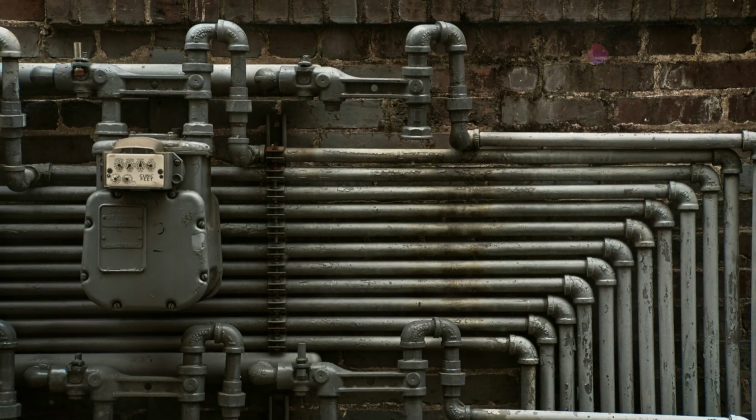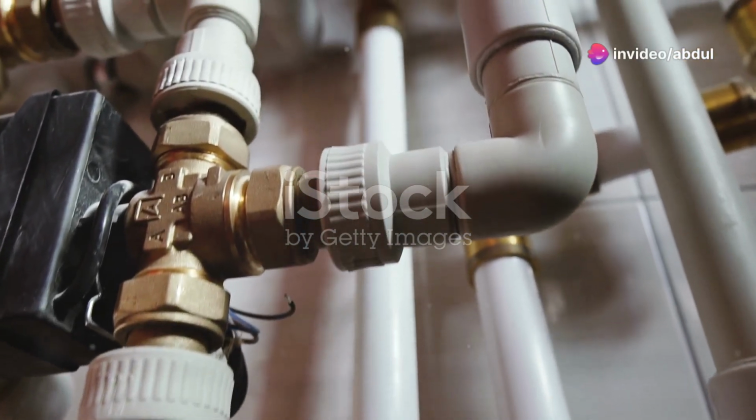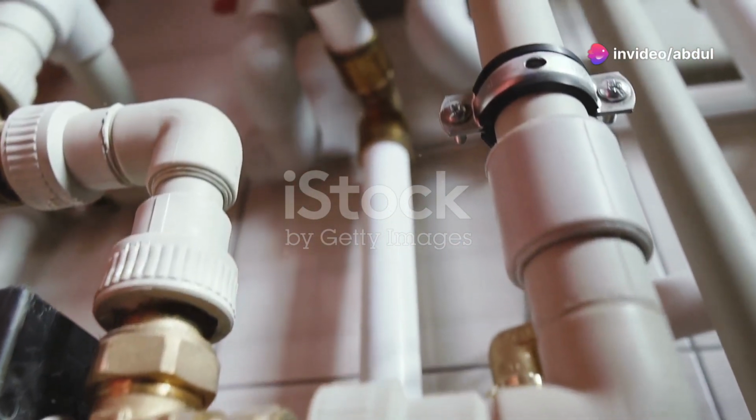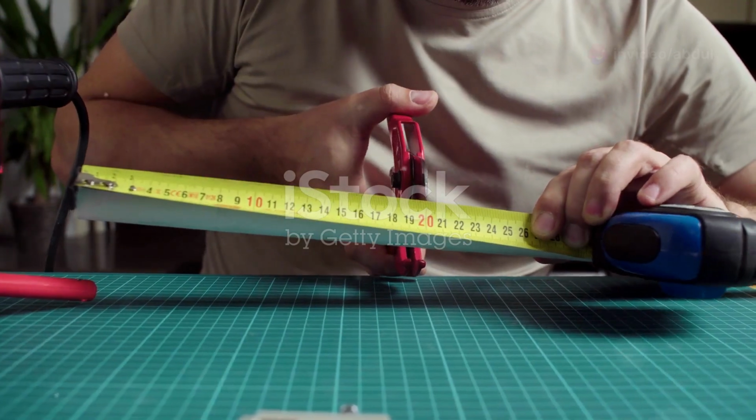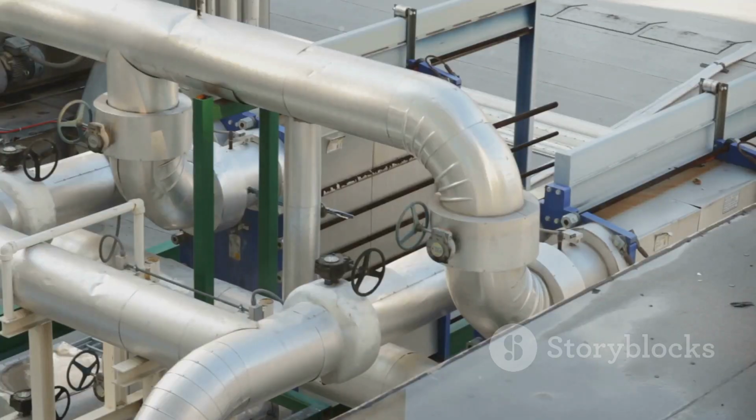First, double-check that all fixtures are properly connected to both the water supply and drainage systems. Ensure that all lines have the correct slope and diameter. Verify that vent lines are properly connected and routed to the exterior.